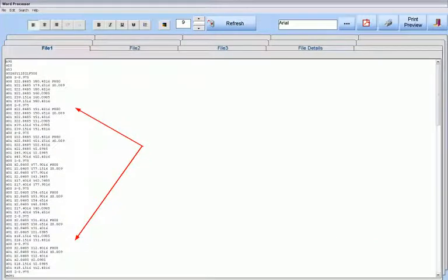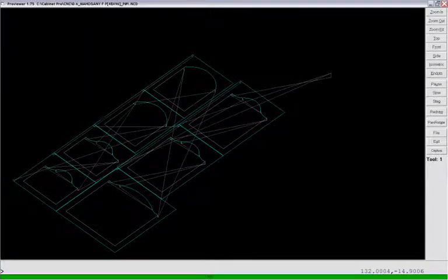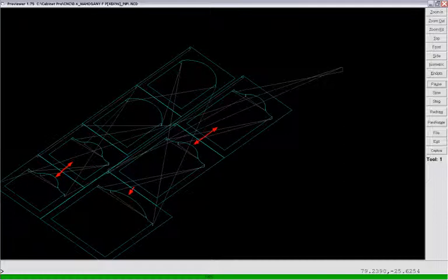And if we are equipped with a CNC router, DoorPro will produce the CNC code, and then machine and cut out the appropriate doors automatically based upon the CNC setup. Here we have a couple of doors optimized on this panel whose tops are oval-shaped, and some that are cathedral doors. In a similar manner, we can assign as much or as little machining per door style so that all we have to do is design our doors at the order entry screen, and DoorPro will automatically place the appropriate machining based upon the door style as well as edge, frame, and panel profiles.